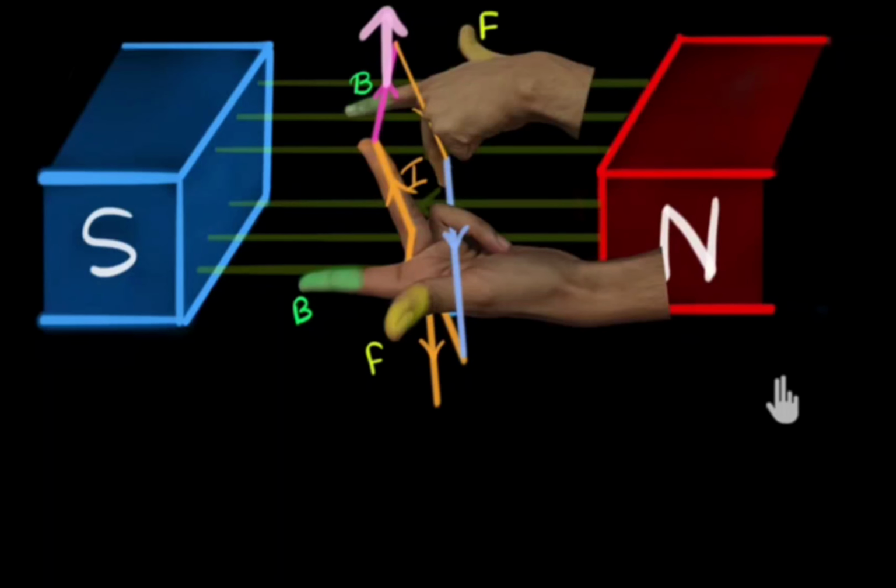Coming to step 3, in the path of the rotation of the armature, a point is reached where the actual position of the rotor is exactly perpendicular to its initial position. That is, alpha equals 90 degrees. As a result, the term cos alpha equals 0, and the torque acting on the conductor at this position is zero.